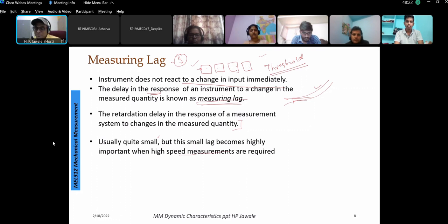But between the time it senses the true value of 200 gram and the action taken, there may be some measurement error. That error you want to reduce. If that error is 1%, then you are going to incur a huge loss, because you are actually filling 1% more over the 200 grams.